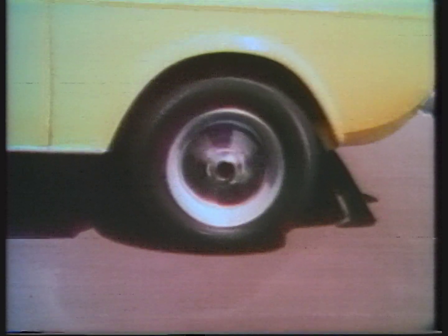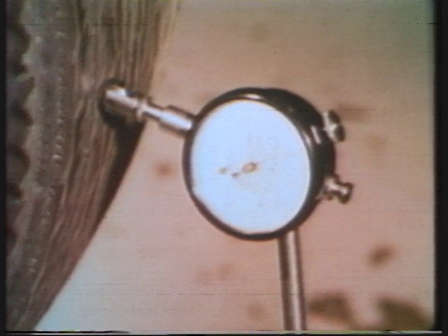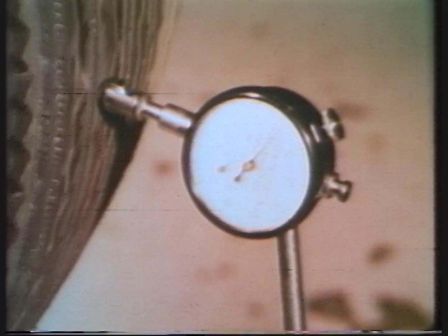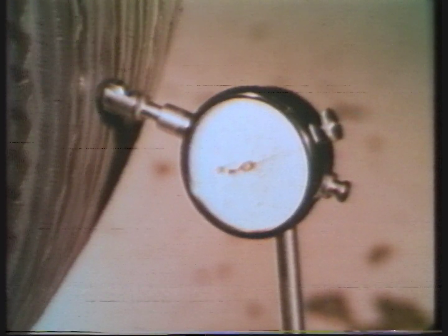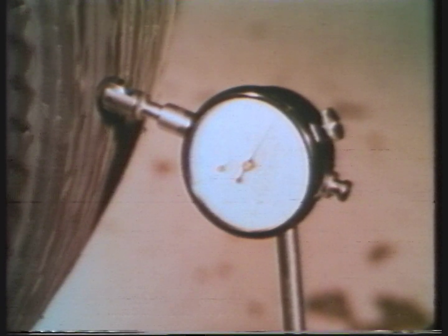Order of procedure must always keep this in mind, deviating only when, say, a tightness check, a quick job out of context, may save time. When working to very close tolerances on a difficult case, remember that wheel runout in turn is dependent upon hub runout and correct mating of wheel and hub faces, etc.